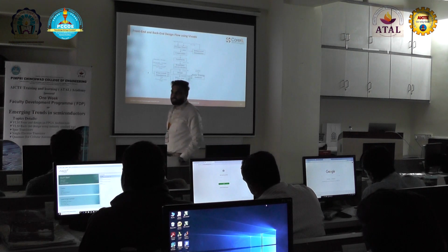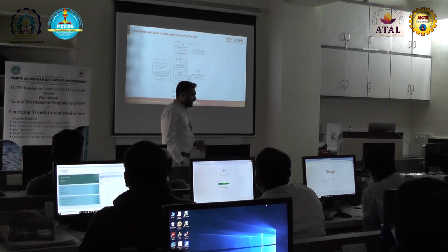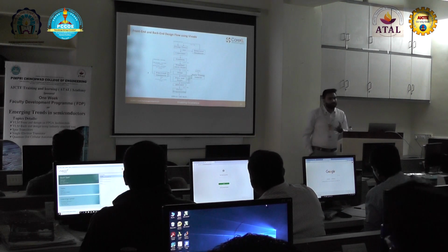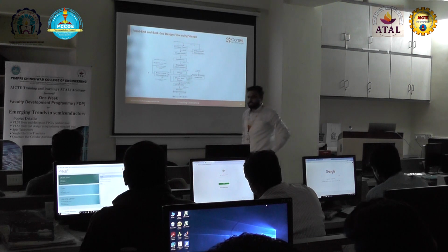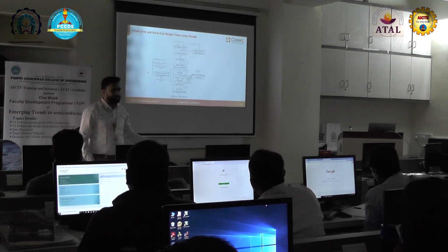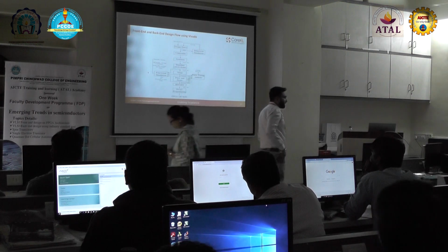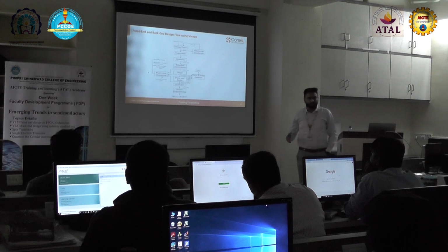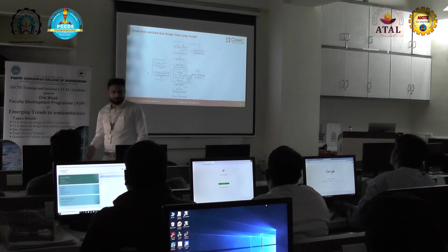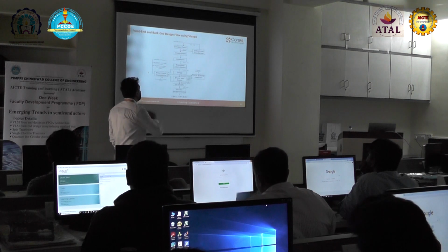All these specifications we are going to take: how much temperature within this circuit needs to be handled, and how much power this system needs. Because if some designs use more power, it will be wasteful. Then they will ask, we need less power compared to this, this is high power. For that purpose, we access this. We can see the utilization of power resources, input-output resources, and clock networks, how many clocks we are using. All of these reports we can take by using Vivado.